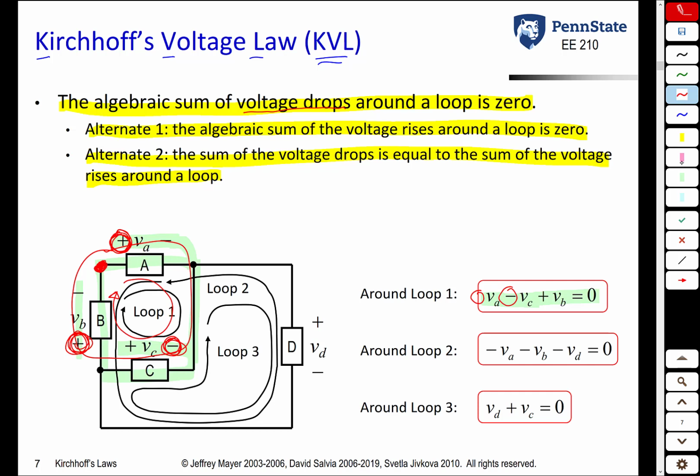Loop 2, let's make it this big loop here. Let us start this one arbitrarily at this blue node on top here. And in this case, I'm going to go counterclockwise. Once again, Kirchhoff's law doesn't care whether you go clockwise or counterclockwise. It doesn't care where you start. All that it cares about is that you end up where you start.